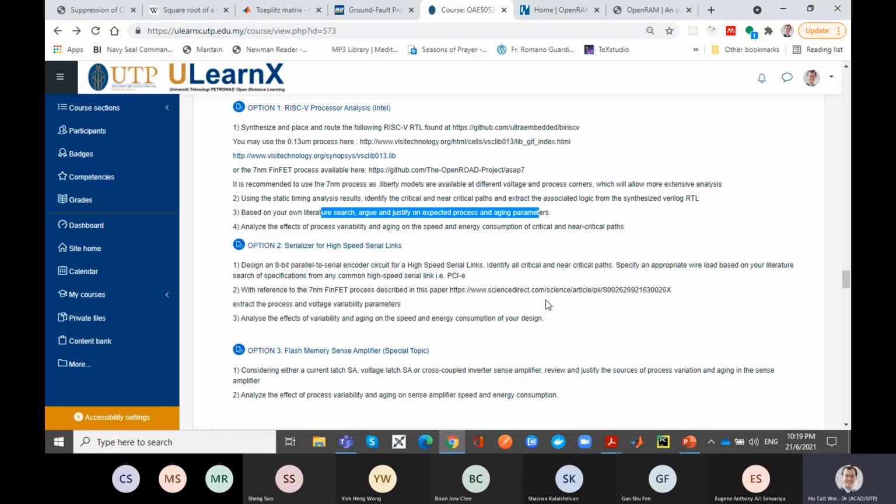Because I understand that for near-critical paths, PVT can make things worse, I actually have to consider these 20 nets. These 20 or 30 nets are the most critical because they are near critical, and any PVT variation will throw them off. So I want to see how you apply the practical aspect of this to identify where the weak spot is in the design that you've built.